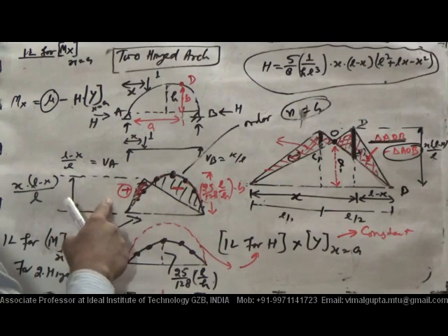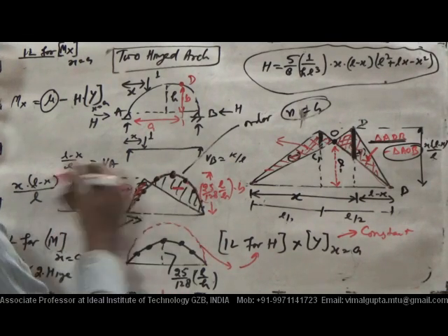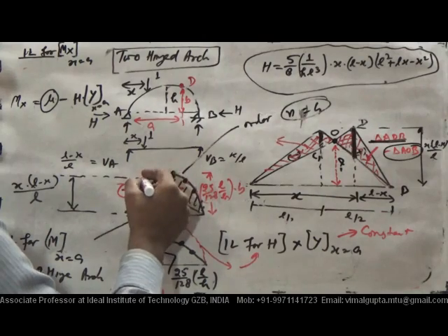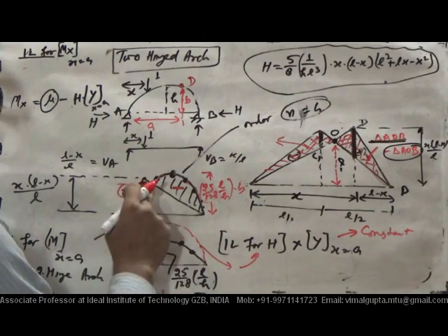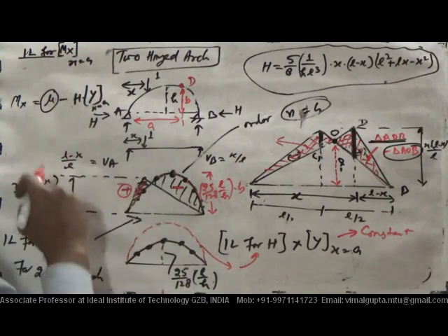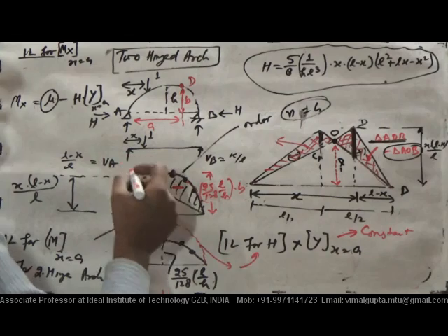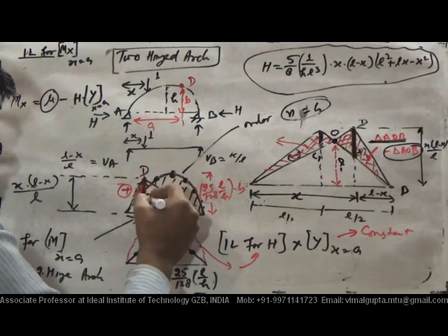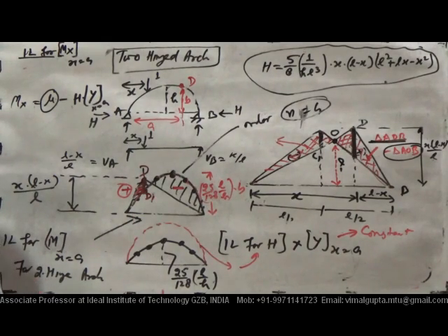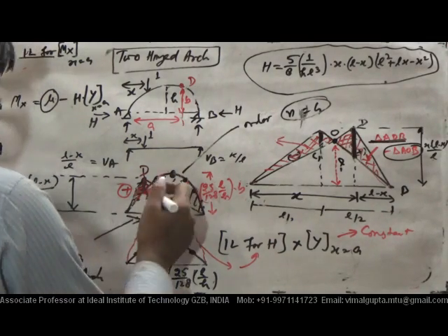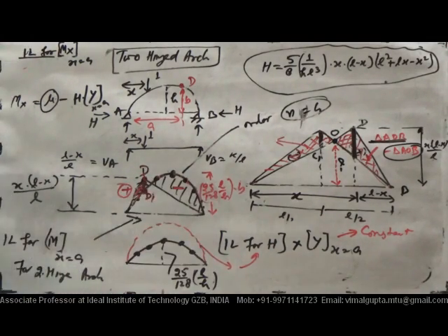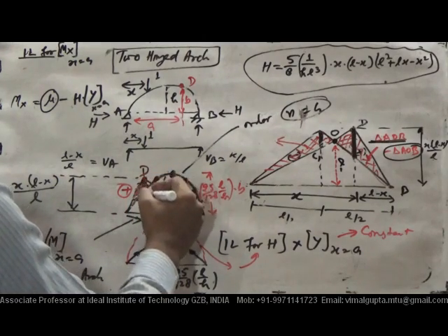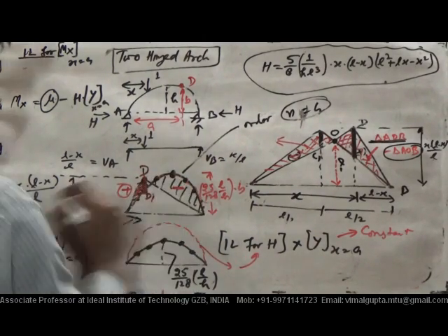Okay. Here I have taken the point D, not here, it is here, point D. Okay, so do not confuse that. So for maximum positive bending moment in case of a point load, it should be placed at the section. And if this is D and this is D1, the value of maximum positive bending moment is the same as in the earlier case. As in the earlier case, it will be W into DD1. Okay, W into this DD1.